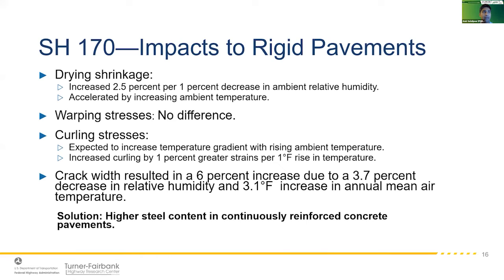How about for our rigid pavements? It shows that the impacts could be on the shrinkage or curling stresses. The solution for this specific case was to use higher steel content in basic continuous reinforced concrete pavements.